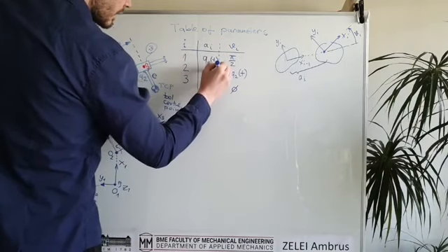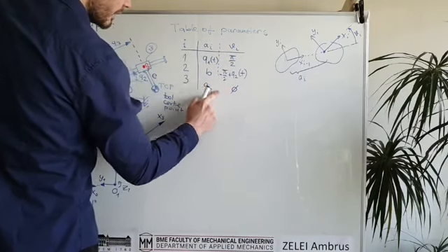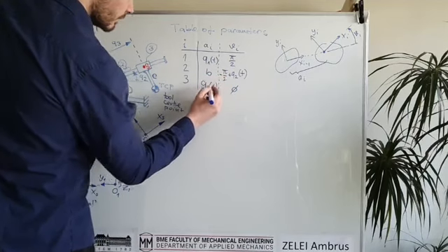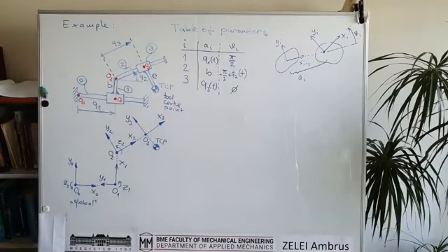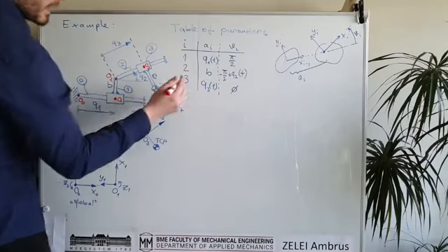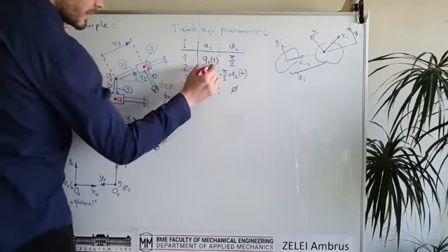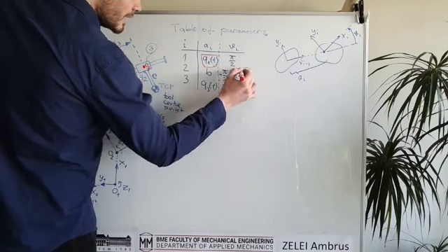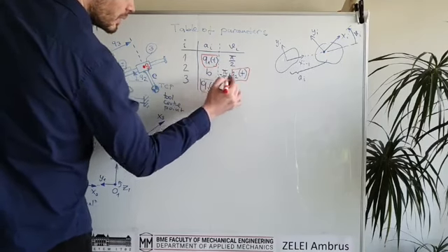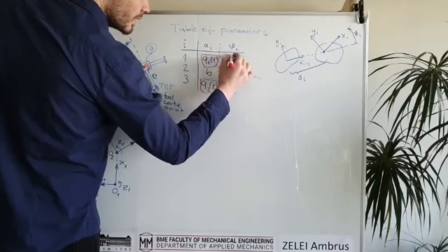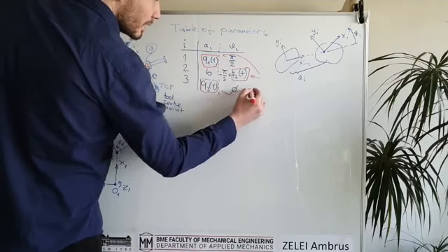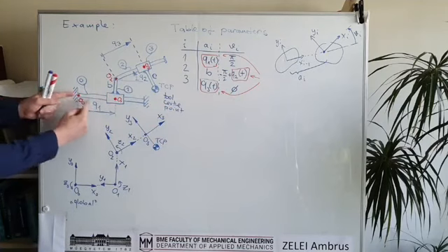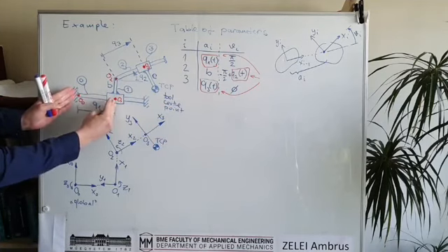So this is what we basically have, Q3. And the important thing is that for each transformation there is one parameter which is time dependent, and these time dependent parameters are the so-called joint variables or joint parameters, because these are representing the position of the joint, which is really a distance or an angle.